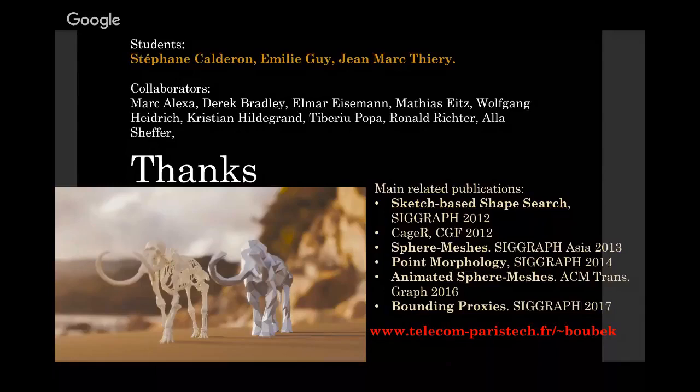If you refer to this particular work I've been showing, we kind of solved the problem because the simplification resolution at which we work is tied to the closing resolution. We first go through a volumetrization of the shape and then perform the closing at a certain resolution that we aim to reach with the simplification, thus most of the time we never encounter the problem. It actually solves this self-intersection problem, because once you're in the volumetric space, in the voxel space, sorry, the closing will basically either delete or merge together the fin structure, and then you mesh that.